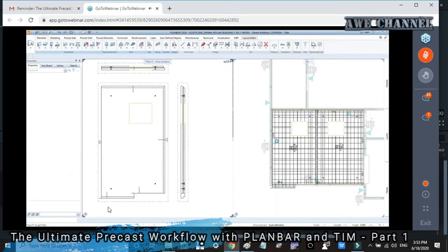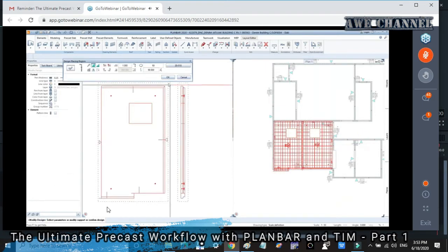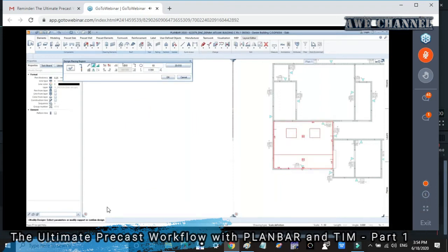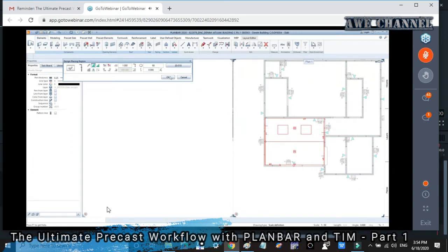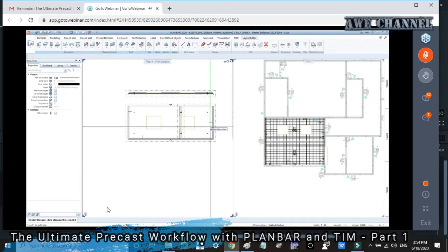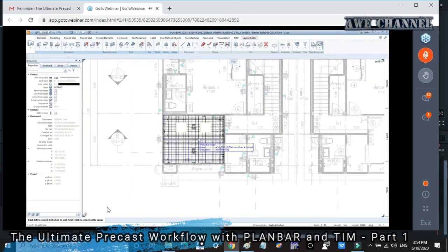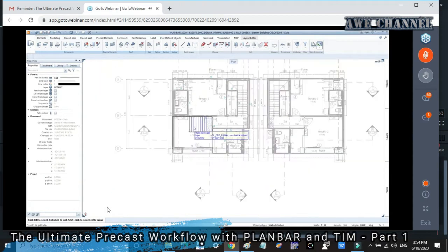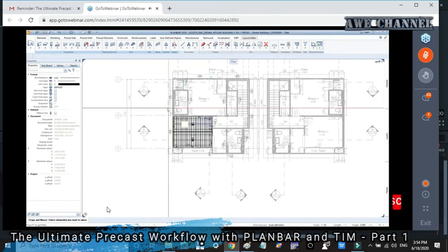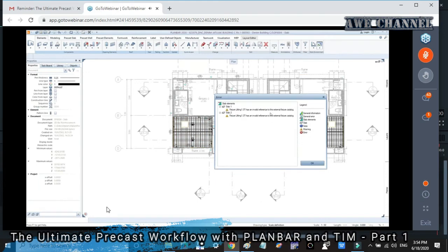And the other thing is, if you are not fine with this slab direction, you just go to span direction. In the span direction now, I want to go to 0 degree. And then I go to set fixed point, make element division here. I'll say OK. So you can see now our solution is very easy to make the modification, update all the things that you have to do for the slab, for example, opening, and of course I just delete opening and the rest will be updated. And if you want to copy it, it's really easy actually. You just copy or mirror, and now you will get a slab like this.